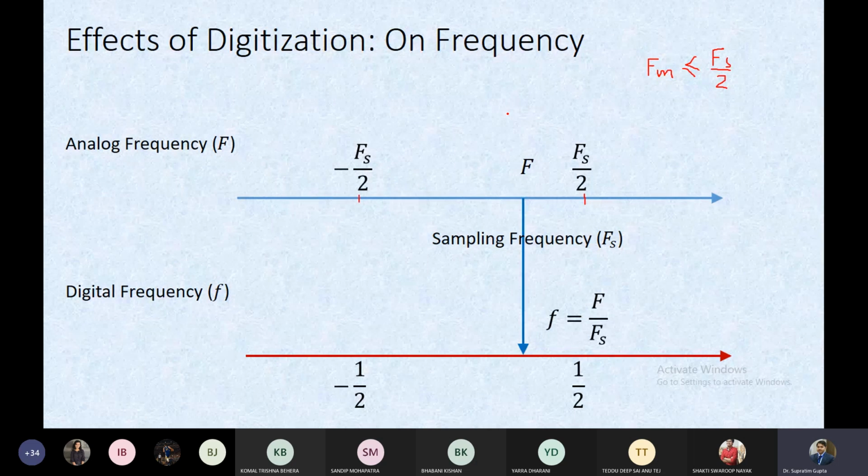If we do not need any reconstruction, and we only want some information extracted from the samples, then this Shannon sampling theorem may not need to be utilized. We can do some tricks also, which nowadays is called compressed sensing, with which we can reduce the sampling frequency further. But whenever there is a requirement of reconstruction of the signal, these limits are to be followed.